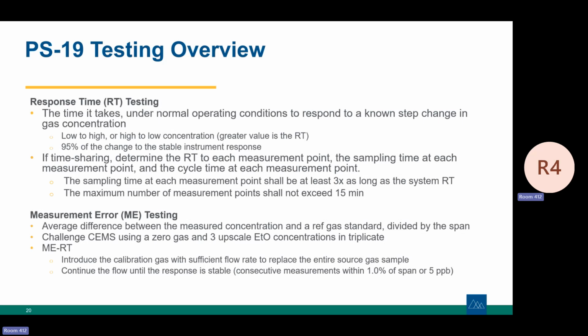Similarly, measurement error testing, the difference between measured concentration of a reference gas and your measured gas. Challenge it using 3 different upscale levels, so low, medium, high. Run that in triplicate, calculate your measurement error and response time. Pretty straightforward.